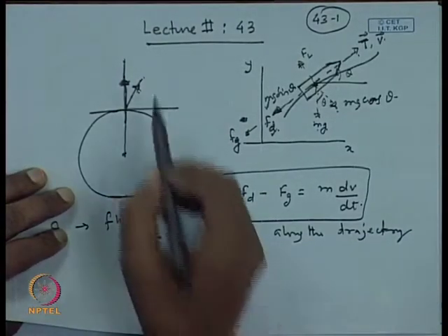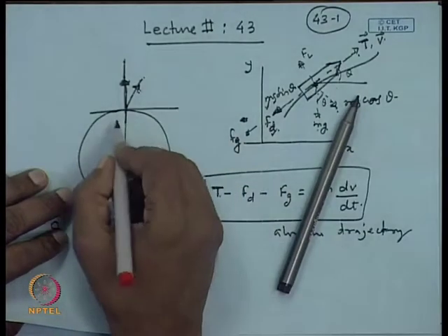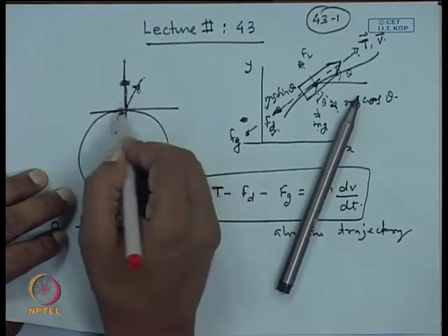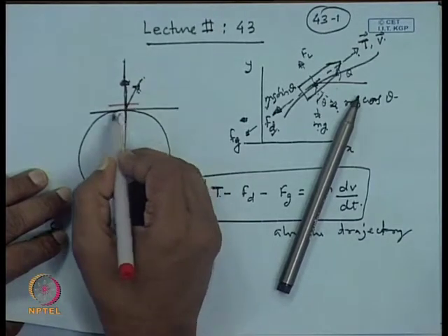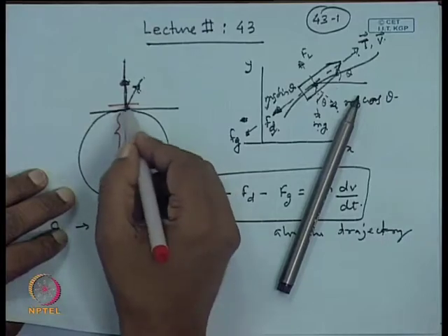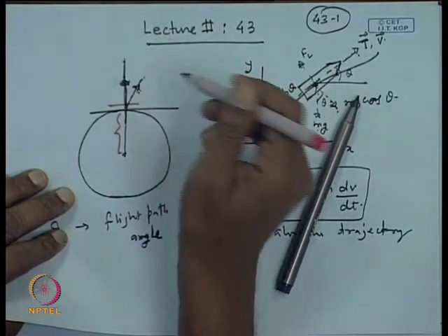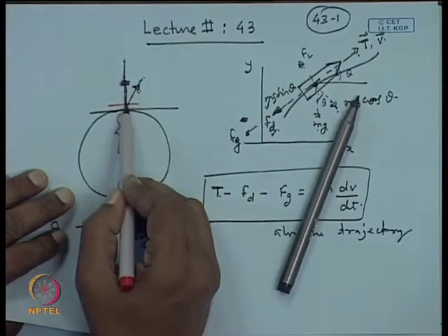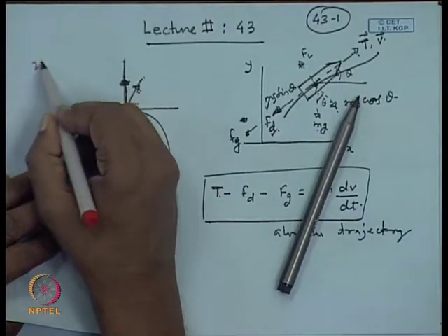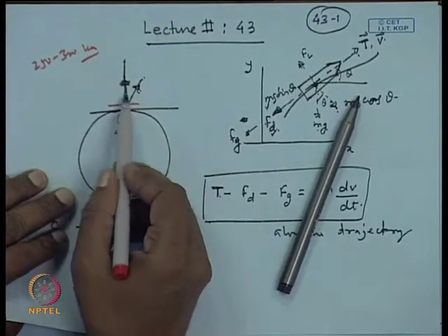In our case, as I have told you, compared to the radius of the earth, the spacecraft will be confined to a very narrow region in which it is being launched. Later on the height may be increased, as in the case of the geosynchronous or geostationary satellite. Initially they are launched at a perigee position of say 250 to 300 kilometers, and later on the perigee is boosted.